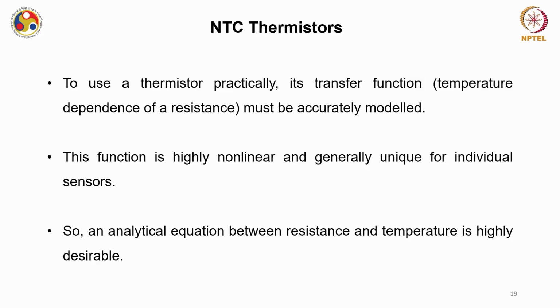So to use a thermistor practically, its transfer function must be accurately modeled. When I say transfer function, I mean its resistance, which of course depends on the temperature. So resistance versus temperature, that data you should have. This function is of course highly nonlinear and generally unique for each thermistor.